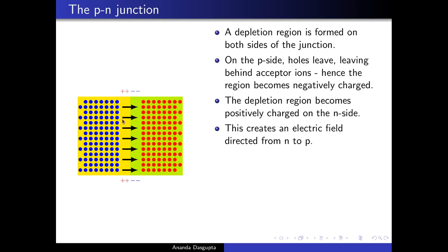Now, if an electron hole pair is formed deep inside the n-type semiconductor or deep inside the p-type semiconductor, they may drift around a bit, but before moving very much further, they will meet. The electron hole pair will have an electron. The hole will move around a bit and then meet one of these electrons and kill itself, leaving the number of electrons the same as before. So that really is not going to contribute anything to the picture overall. But an electron hole pair formed here is a different story.